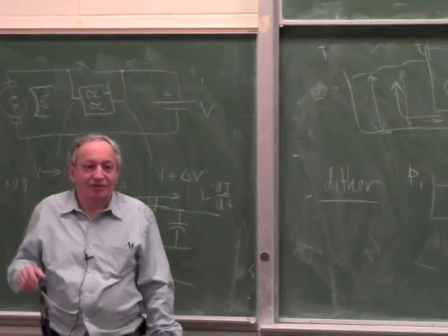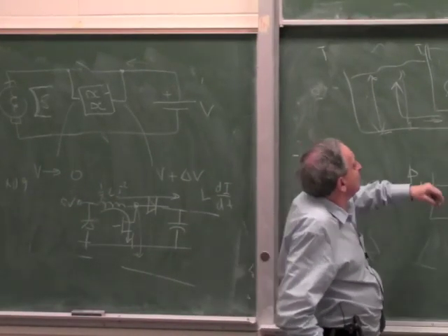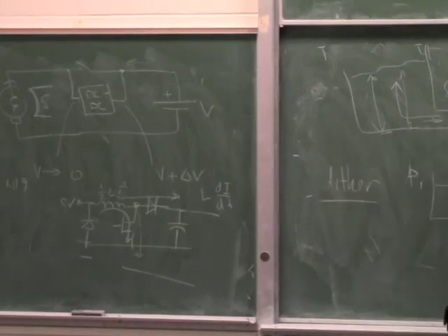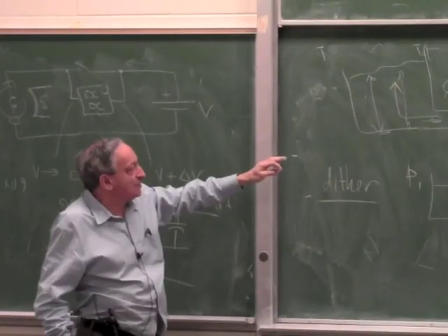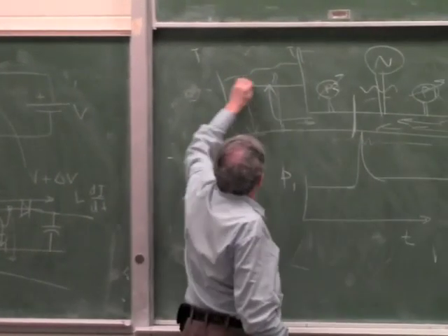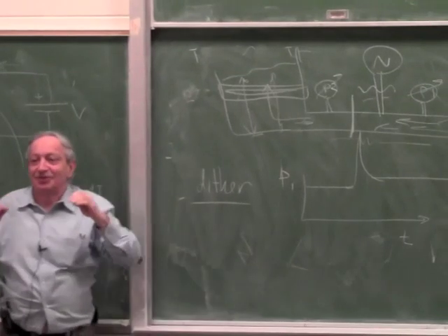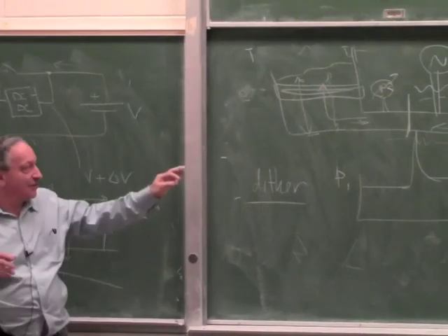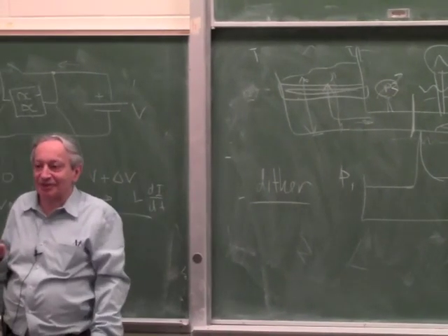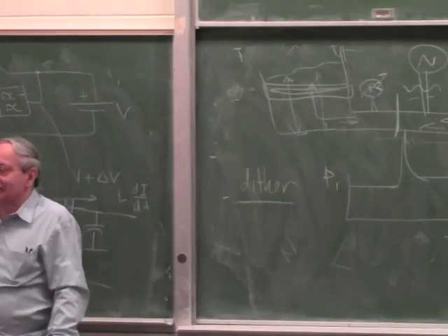So the way you solve it, you put a small AC signal into the servo. So let's say you have a pump here, and that pump just gives you a pressure pulsation, or a sine wave, small variation in pressure. So what this means, that wherever you have some pistons in the system, these pistons are always vibrating, so they don't have static friction. Okay? And that's a very powerful technique. Without that, you cannot actually build a high-performance hydraulic servo. So that's called dither, and that is also used in electrical servos.